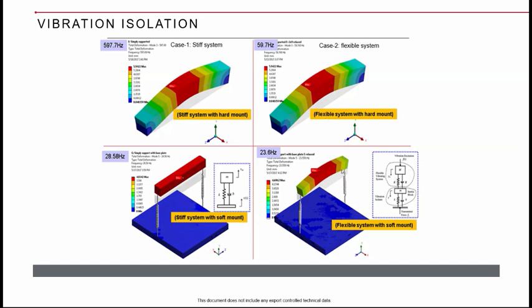So you have to sufficiently define the softer spring so that you will not end up in this kind of relative deflections. So the flexibility of the system should also be accounted for when you are designing the spring, when you are dealing with a flexible system to be isolated. Okay.